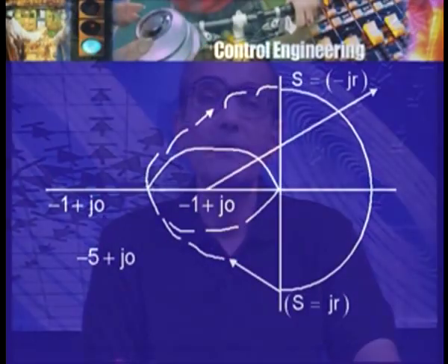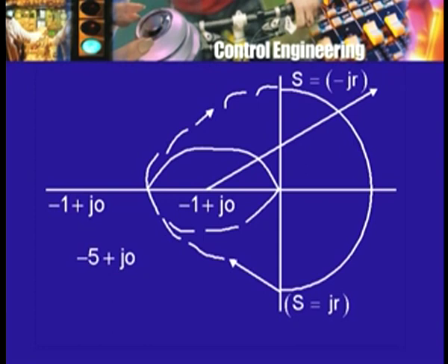That is, no matter what change in the torque takes place in the steady state, there will be no steady state error in the speed if we have integral feedback. But as we saw earlier with the root locus method, with the use of integral feedback, there was this possibility of instability if k becomes too large. Now, we can see that using the Nyquist approach also.